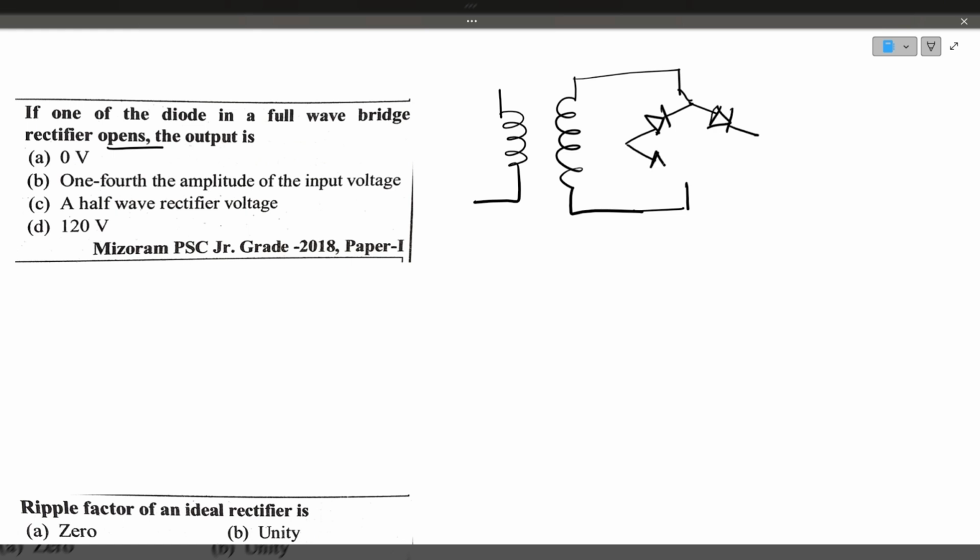Simultaneously, what happens? For the positive half cycle, two diodes conduct. For the negative half cycle, another two diodes conduct. This is the principle of the bridge rectifier. If any one of the diodes fails, see here, during the positive half cycle...